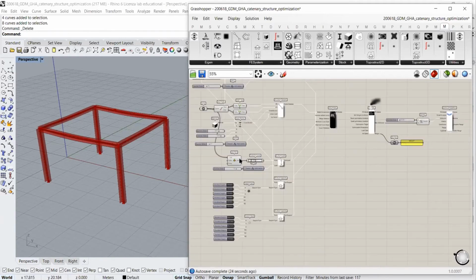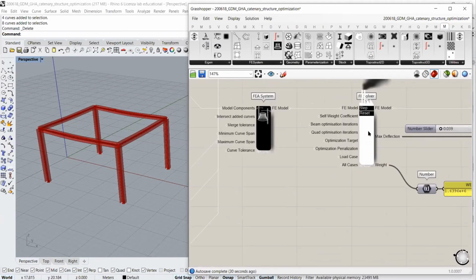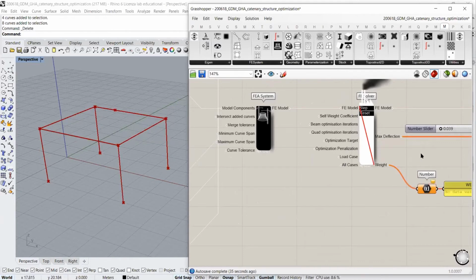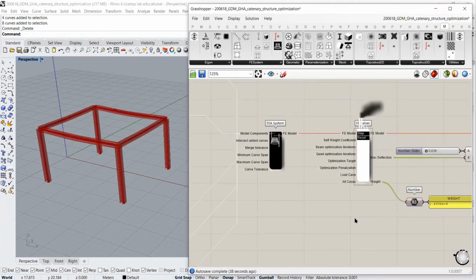So in that case, what I normally recommend is that when you want to tweak parameters in your system, you take the solver, Control E the solver, so it doesn't calculate anything. Then you do all the changes that you want, and then you reactivate the solver. Now, in this case, you see the result is almost real time, instantaneous.